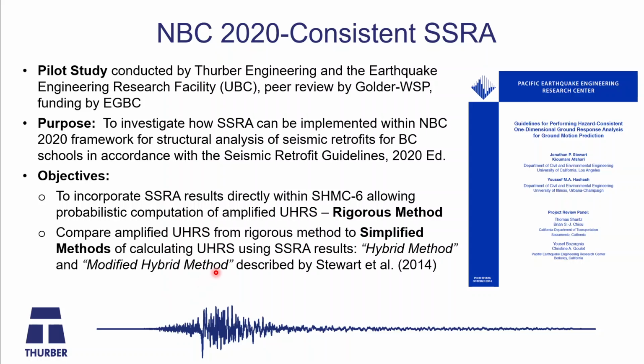And the purpose was to investigate how we can implement site response analysis into an MBC 2020 framework, in this case for structural analysis of seismic retrofits for the BC schools in accordance with the 2020 edition of the Seismic Retrofit Guidelines. So the objectives of this particular study were, one, to incorporate the SSR results directly into